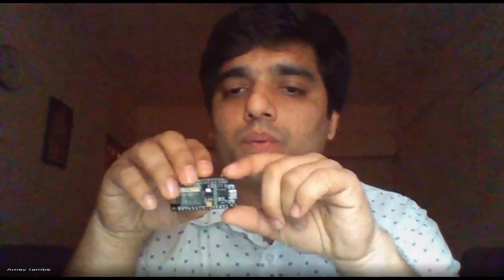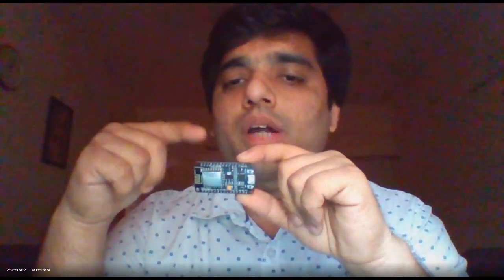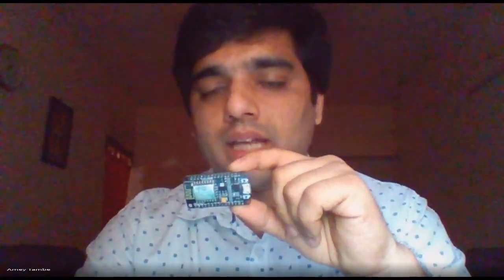But before that, we will be connecting our sensors through the main Node MCU, and we'll try to collect as much information as we can get. So this can be in an access point mode, and 5 devices can get connected to this Node MCU. Now another mode is the client mode. It means this Node MCU will not have the ability to provide a connection, but instead it will connect to the existing access point.